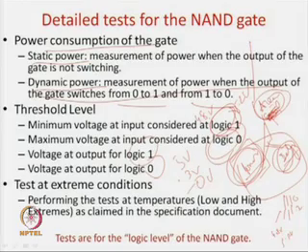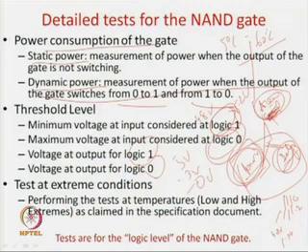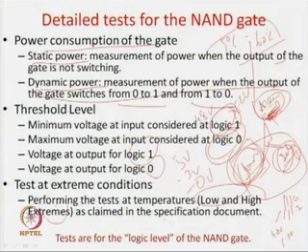Now, your circuit can be subjected to another set of tests. It can be subjected to very extreme conditions. We say that your VLSI circuit or device will work properly, for example, from say 5 degrees centigrade to around 60 degrees centigrade. We generally write that, so your device will work properly within so and so temperature. If it is military grade equipment, we say that it operates from minus 60 degrees centigrade, just as an example, may not be correct, but from some minus x degrees centigrade to some plus x degrees centigrade. So, all the tests I have done now have to be done at the low and high extremes, which is actually claimed in the specification document.